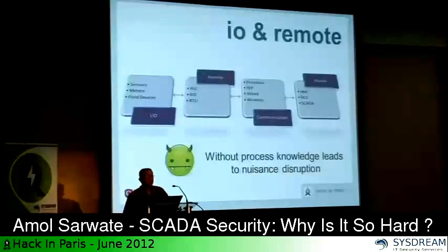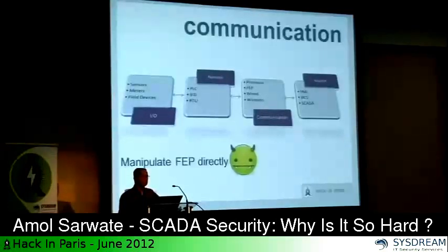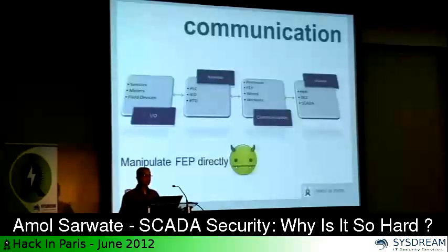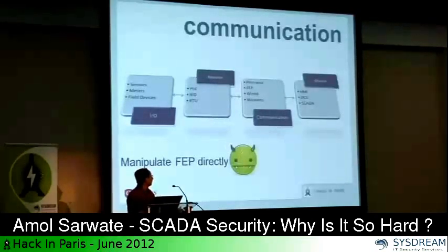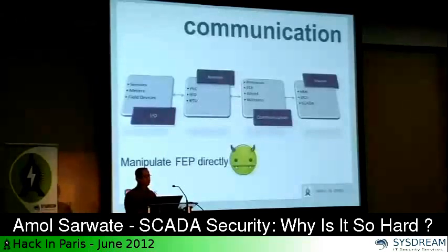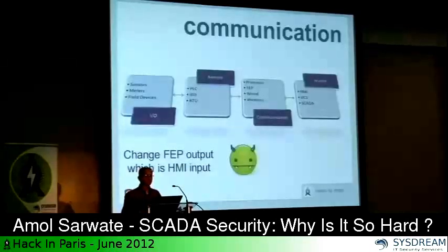So what we did was we said, okay, let's focus our attention on the next vector, which is the communication vector, which is how data gets communicated from PLCs to the master units. There are various attack vectors here. If a man in the middle happens here, then you can manipulate the FEP output, and the operator would see something different, would see that some valve or some circuit is open when it's closed, or closed when it's open, and so on.